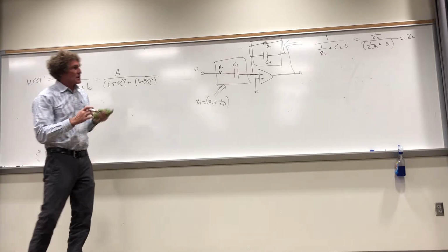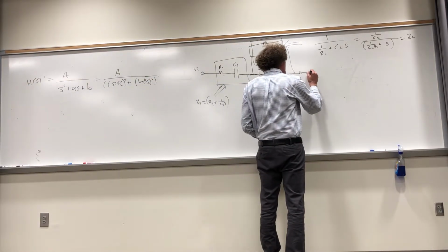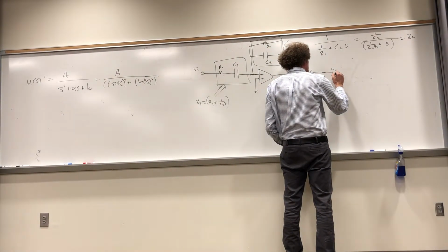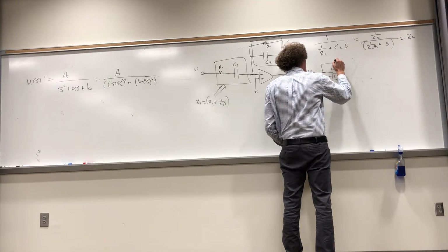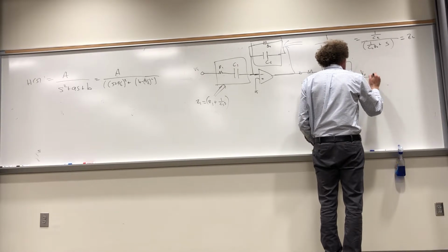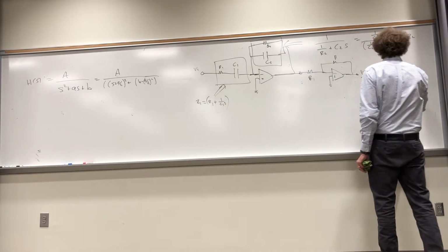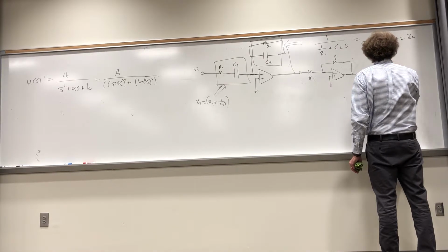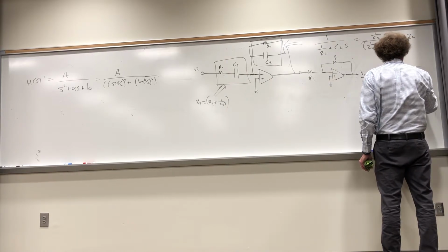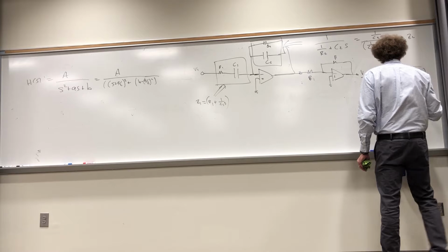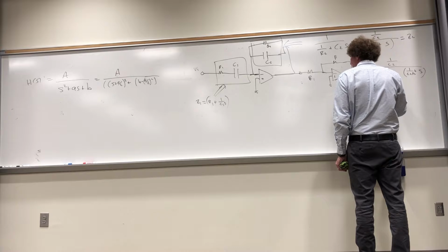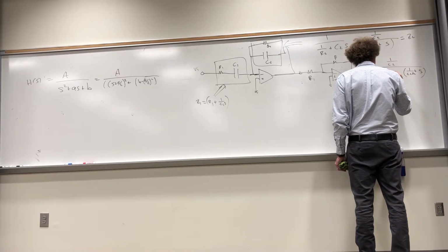Now with this, I'm also going to put the inverter right in front of this thing. So I have R, just R here into the negative terminal. Ground that, R here, and they come out, and now Vout over Vin, the transfer function, is going to be 1 over C2 divided by 1 over C2R2 plus S, and then divided by R1 plus 1 over C1S.